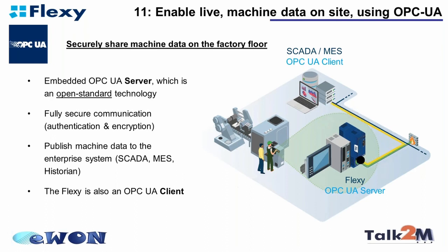They'll be able to connect to the Flexy 205 and pull data back into the SCADA systems, alongside lots of other things that will be existing in the control systems on that site. OPC-UA is totally secure, so this is a very secure way of getting data from a production environment, perhaps up into an MES or into an IT environment.